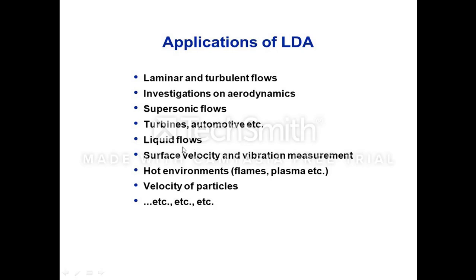Then all kinds of liquid flow, provided it is transparent. Non-transparent fluid we cannot use this for. It can also be used for surface velocity and vibration measurement. You can even use it in a hot environment, if the temperature goes a little above room temperature, you can still measure. The velocity of particles can also be measured, and there are many other applications.